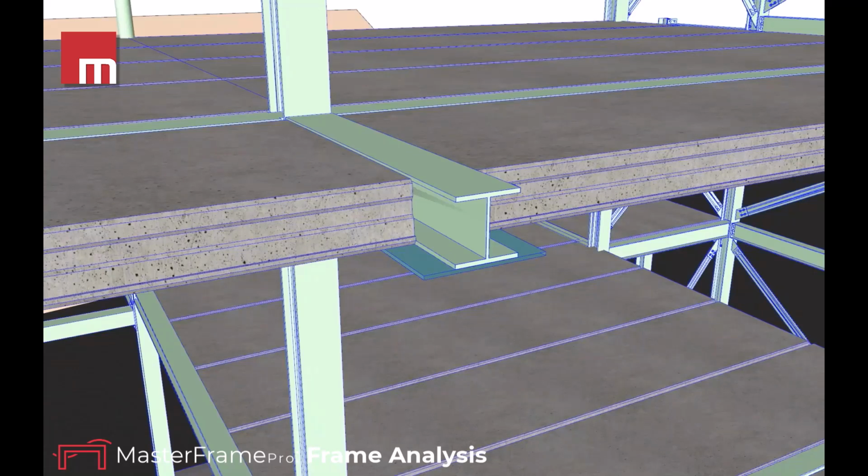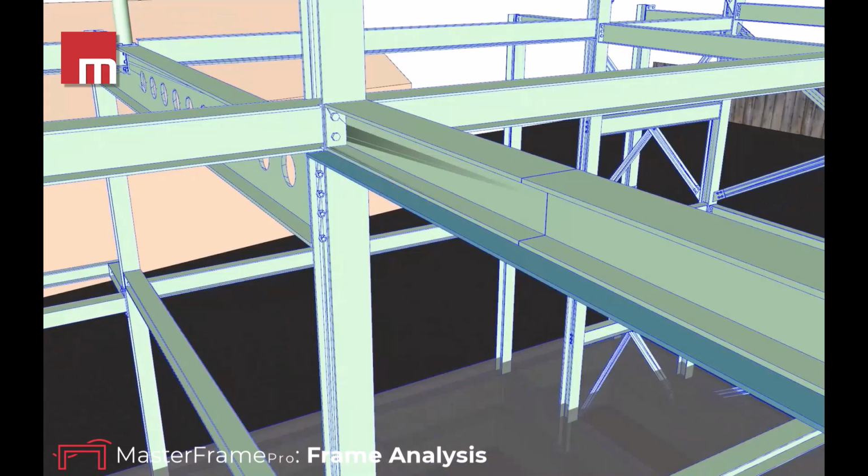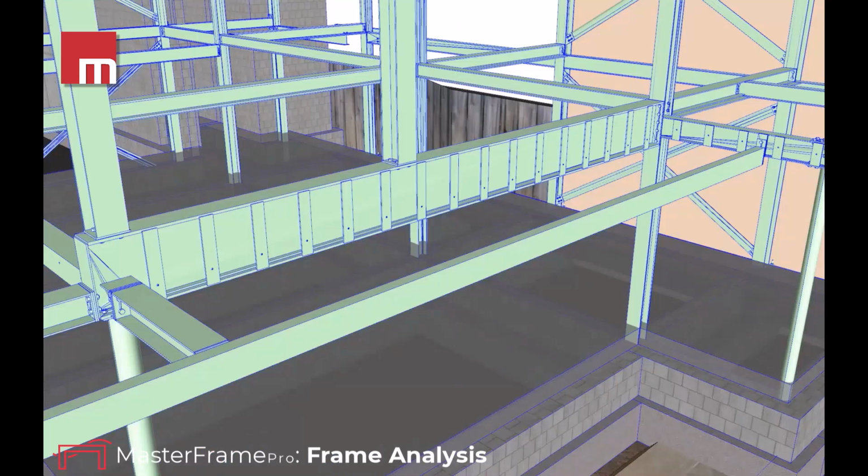We can assume diaphragm action on this floor to be able to model a stiff deck in MasterFrame, but it requires a minimum of a structural grout between the joints. We can also model eccentric loads on members in MasterFrame, in this case for beams that are carrying loads from masonry walls. And for this detail, the fabricator has used plates at close centres welded between the flanges of the beam to take the masonry support brackets. Our steel connection design module as well.